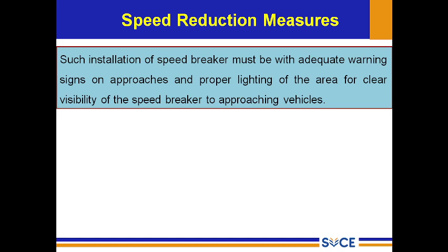The advantage of speed breakers is that they can be easily placed at identified locations. The degree of the effect depends upon the profile, height, gradient, length, and the material we use to construct the speed breakers. Humps as speed reducing devices work on the basis of a slight inconvenience in the form of a jerk and vertical acceleration caused to the driver.